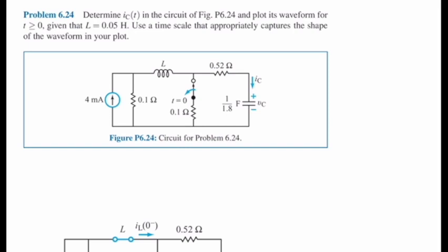So it will be easier to rearrange the resistors when you find RTH. But the first step of just finding series or parallel is to redraw it with the switch open, so the final state for the switch. Series, right? So then you hopefully can see the third series. Did you see the third series?